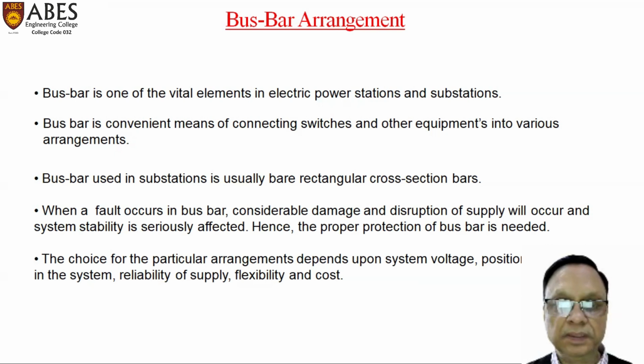When a fault occurs in a bus bar, considerable damage and disruption of supply will occur, and the system stability will be seriously affected. Hence, proper protection of bus bar is needed. The choice of any particular arrangement depends upon the system voltage, position of substation in the system, reliability of supply, flexibility and cost.